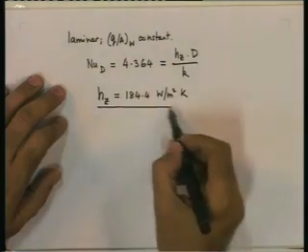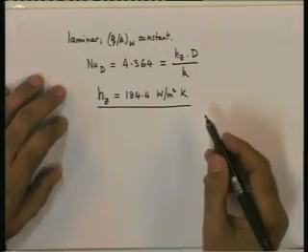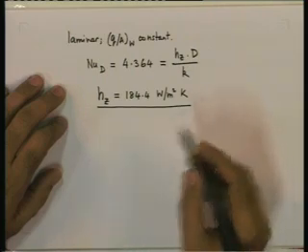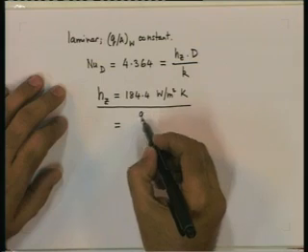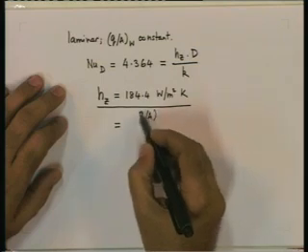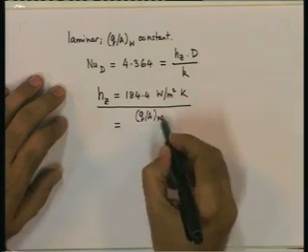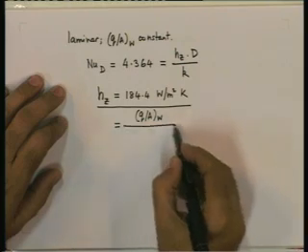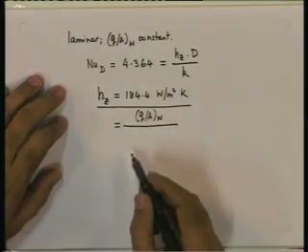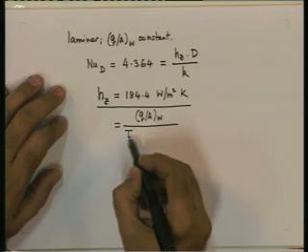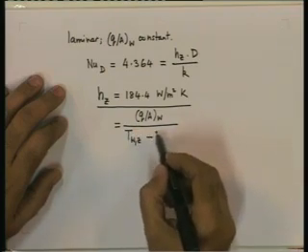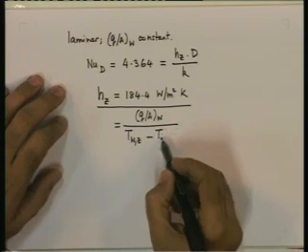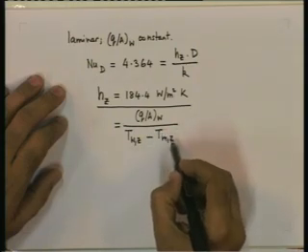That's the first conclusion. Now the heat transfer coefficient itself is the heat flux, it's uniform, so we don't have to use the subscript z, divided by the wall temperature at that location minus the mean temperature at that location.